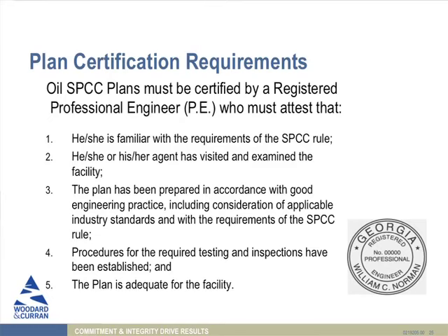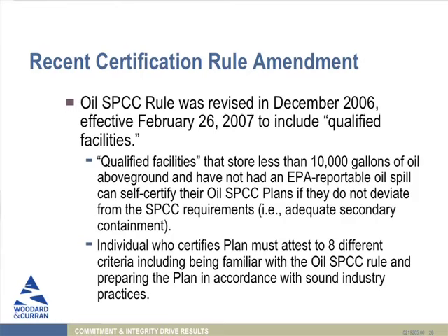Your SPCC plan, in most cases, we'll tell you the exception in a minute, needs to be certified by a registered professional engineer. And when they certify it, they're going to attest to these 5 different criteria. Don't have to read through those. The exception, though, again, this is another new rule that came out December 2007. Just like the qualified operational equipment where they gave you a little bit of an out with that general secondary containment requirement, EPA now instituted qualified facilities.